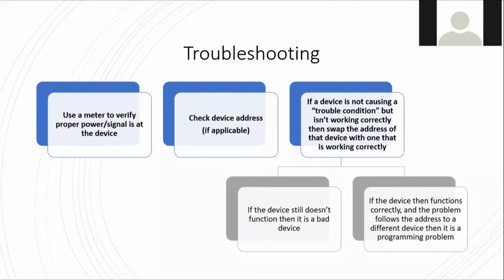Okay, here we go. All right, Ramsey, what you got? On the devices for the elevators, like the smoke detector, I know you were saying that the heat detector has to be within 2 feet of the sprinkler head. Okay, now for the location, as far as the lobby smokes, how far do they need to be to the elevator? Or how far away can you go away from the elevator?